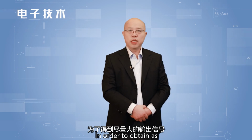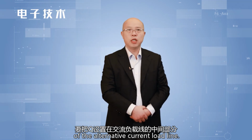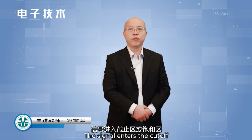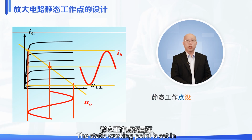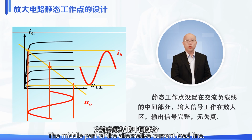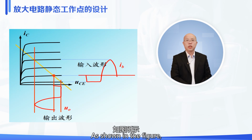In order to obtain as large an output signal as possible, the Q point should be set in the middle part of the alternating current load line. If Q is set inappropriately, the signal enters the cutoff region or the saturation region, which will cause nonlinear distortion. As shown in the figure, a static working point is set in the middle part of the alternating current load line. The input signal works in the amplification region. The output signal is completely distortion-free, as shown in the figure.